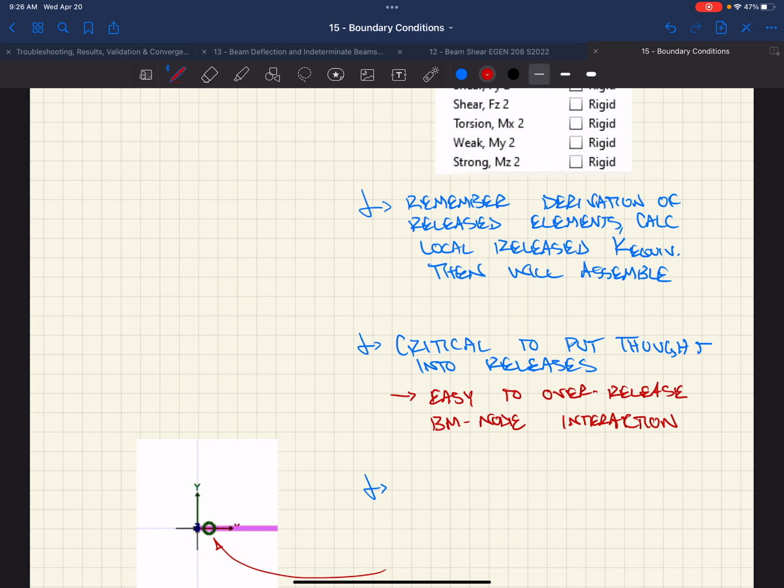And then in VA, the interesting part is we're not really going through the design module too much, just because you guys are at different levels of design of members. But in VA, it becomes important with respect to the K factor. Because when VA looks at a column, it looks at it from end to end, the 2 nodes that make it up. In VA, you can establish brace points for the Z-axis based on intersecting nodes. So even though you have a node here, VA might look at this column as one big tall column.